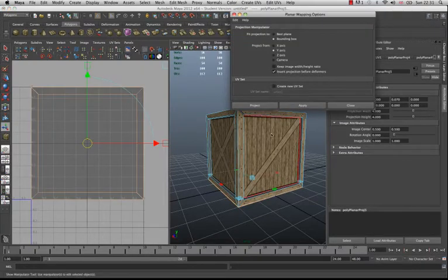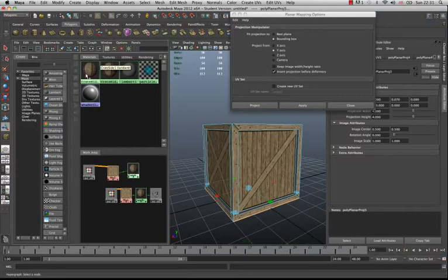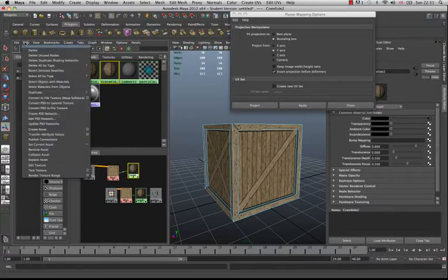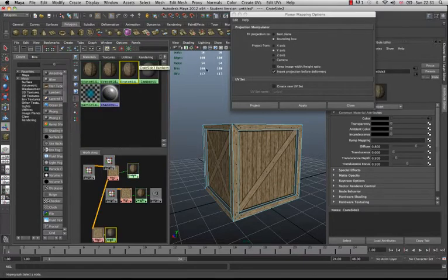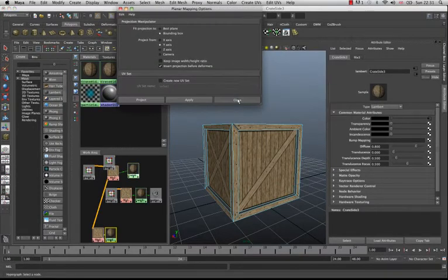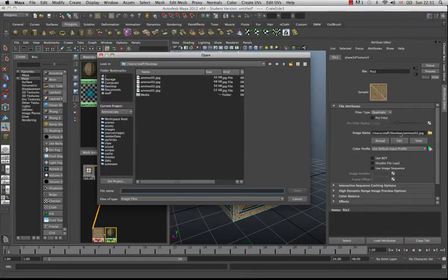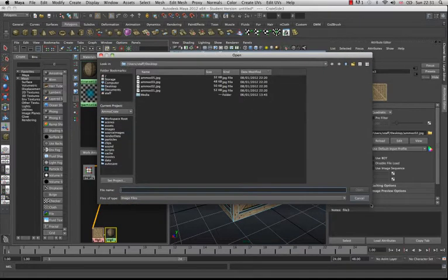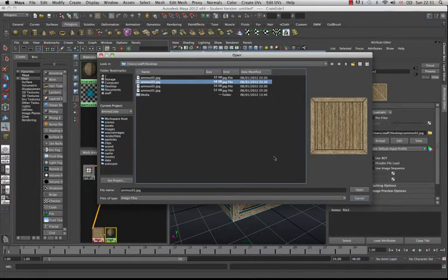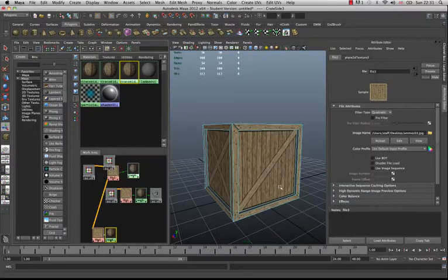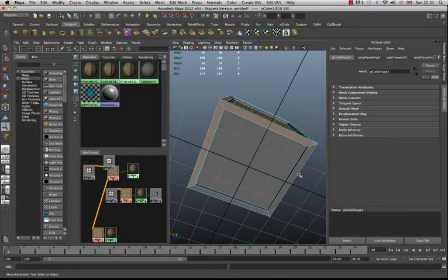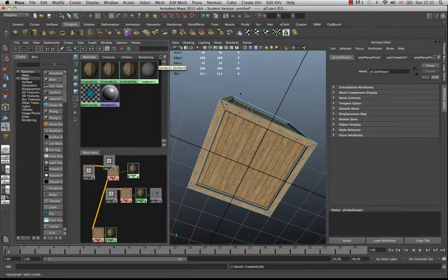Click apply. And let's create a new material. So we can select shader side 2, select this material, go into duplicate shading network, so we get create side 3. Just close that down. And create side 3 will just open up. We'll go find the file. We should get a preview when we do this, so let's have a look. There it is. And that's the one we want, the plain one. Click open, and select the bottom faces again, and right mouse click, assign material to selection.